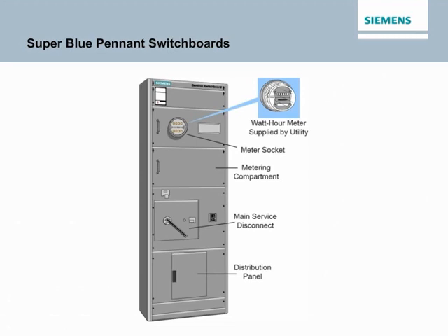current transformer compartment. The main service disconnect can be a fusible 400 or 600 amp vacuum brake switch with a maximum interrupting rating of 200,000 amps, or a 400, 600, or 800 amp circuit breaker with a maximum interrupting rating of 65,000 amps at 240 volts and 50,000 amps at 480 volts. Distribution kits are optional and field adaptable with ratings of 400 to 800 amps. Up to 40 branch circuit provisions are available with an 18 branch circuit minimum.